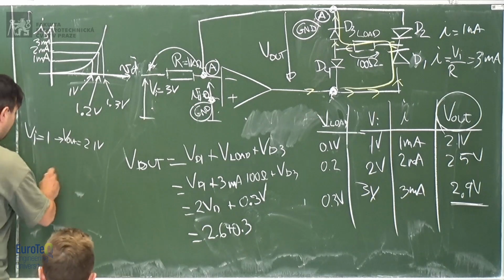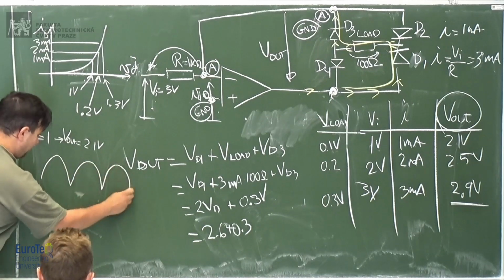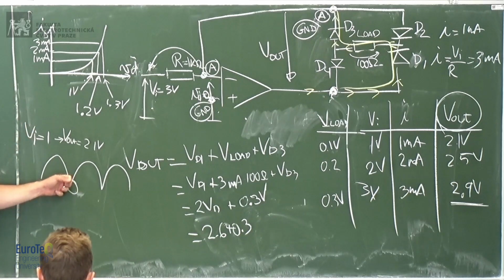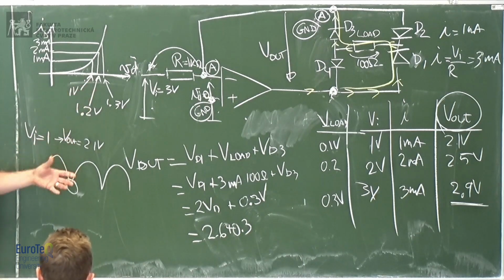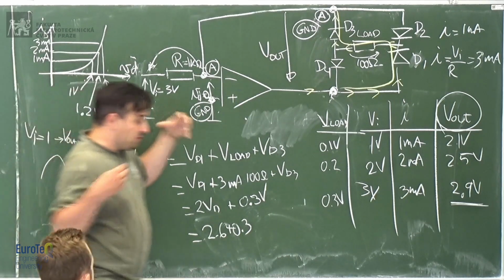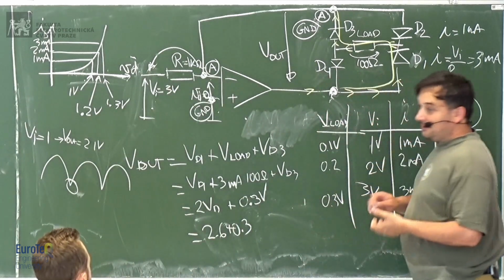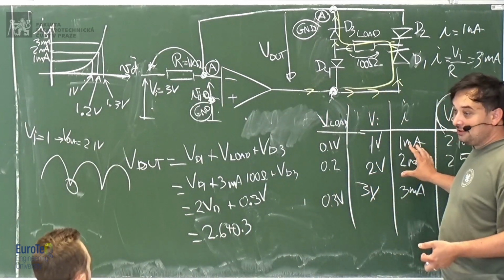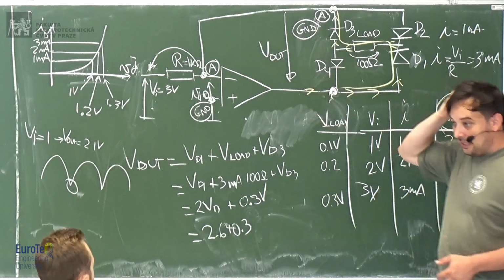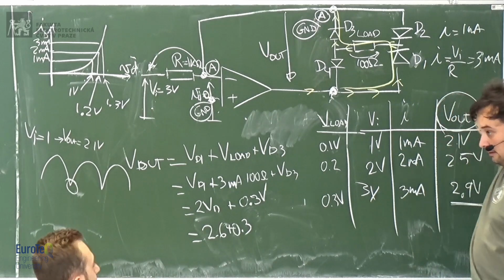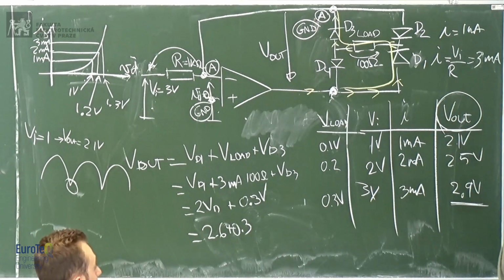Okay, so in this case you can make a perfect rectifier which works fine also for the low voltages, because where you are here close to 0, you have to compensate all this nonlinearity, and you can do it because you have this operational amplifier which is able to generate the correct extra voltage which will go on the diode every time. Does it make sense? Sure, 100%. Okay, cool.